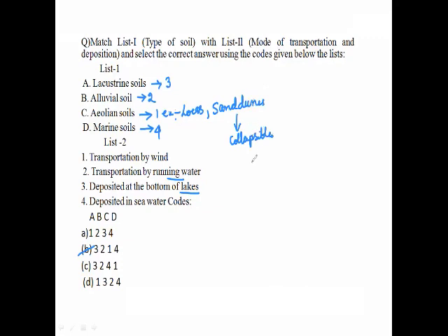Again, we need to know some other types of soil. They are nothing but what we call marl and muck. Marl as well as muck. So what is marl? Marl is a fine-grained calcium carbonate soil of marine origin, which is found due to the decomposition of animal bones and aquatic plants, and it is greenish in color.